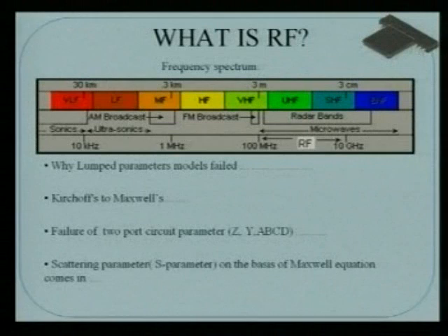So roughly you can say from say 100 megahertz, because you know the online video streaming, now it is the DVB-H for handheld cell phones that will also provide you the video. Then the frequency range is around 472 to 670 megahertz. So from 100 megahertz roughly at the lower range and up to 10 gigahertz is the domain of the RF. And above RF, it is the microwave and the millimeter wave regions.